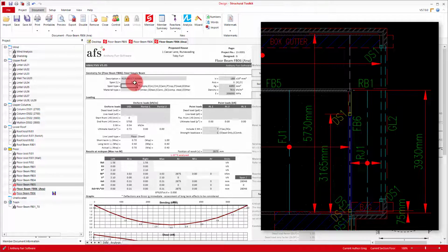We'll go from left to right, so starting with our full span UDL input, if we look at our plan, we can see that the only consistent load we'll have across the entire span is some amount of roof. As the roof joists don't span into the beam, the most load you get on it is the centres of a joist, being 900. Although technically the southern part isn't even 900, going halfway to the garage lintel, to keep things simple, we'll use 900 centres of roof along the entire span.